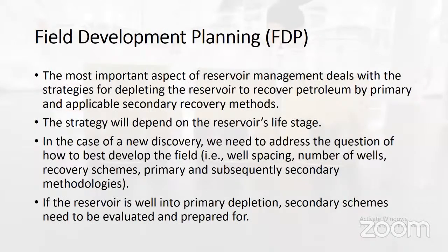So again, for the field development planning, we are focusing on some items to be determined, like the well spacing, the number of wells, and the recovery schemes. If we apply water injection or gas injection, what is the optimum gas injection rate? What is the optimum water injection rate? What is the optimum production rate? Because in some cases we have fields that are very near the bubble point.